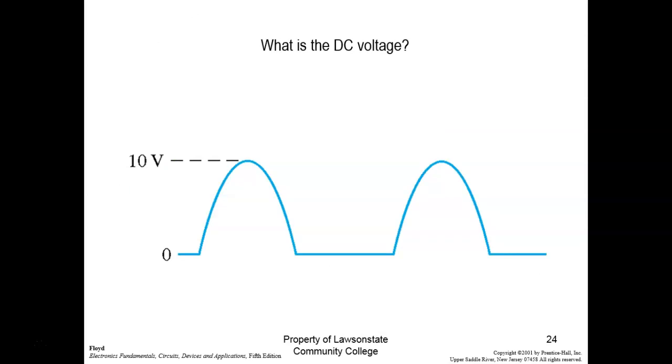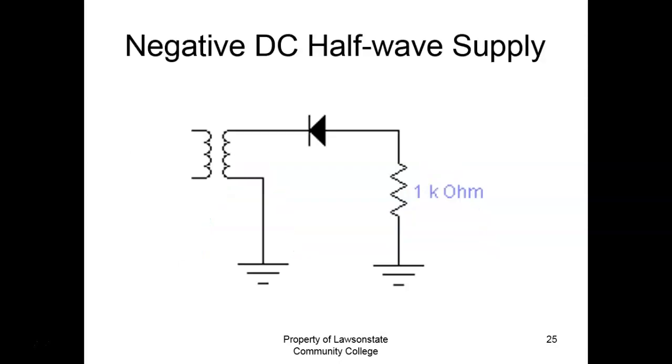So this is DC. What would my average DC output be? What is the DC voltage? So we don't have to take off the 7/10 because this is the DC, right? Did we do this one already? I think we did 100 volts. This is going to be 1/10 of that last answer. So what would my DC average be? 3.18. Everybody okay? Everybody okay on the negative?